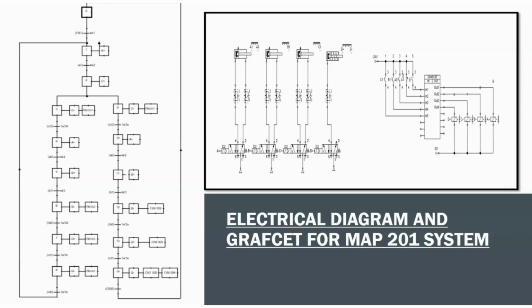There are 2 types, the incorrect position and the correct position. The incorrect position will start from the initial step 0 until step 8. If the machine detected a correct position, it will start over from the initial step 0 and continue to step 9 until step 14, and it will repeat 3 times. Thank you.